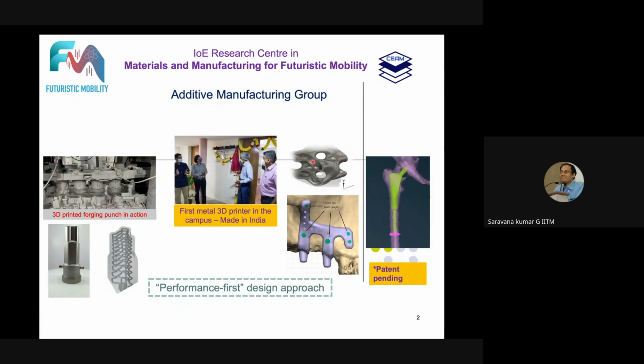So here, as you can see, these are the pathways for, say, the hot fluid, and you have the cross flow configuration where over this tube you have the cold fluid. The design has been optimized, the topology as well as the shape, such that it is able to give enhanced heat transfer with reduced pressure drop characteristics. And many of these biomedical applications, anyway, as part of today's talk, I will be talking.